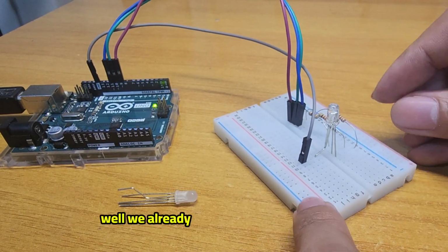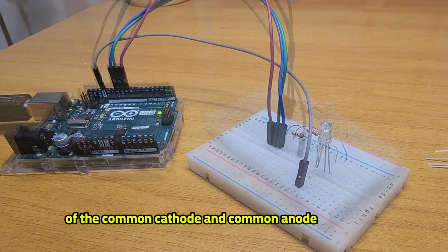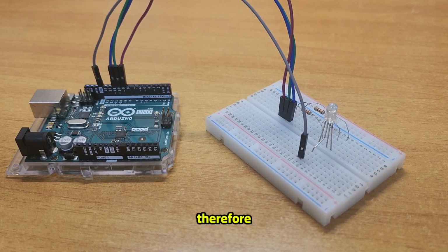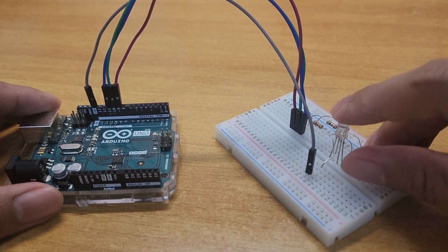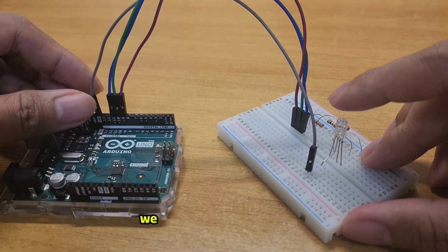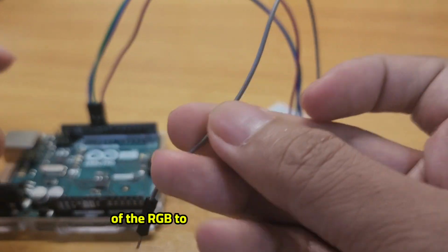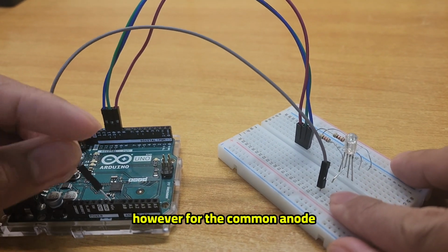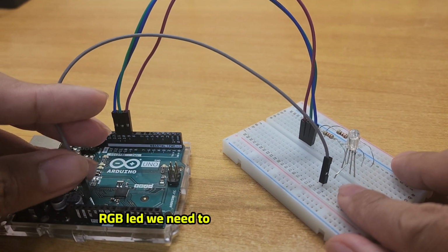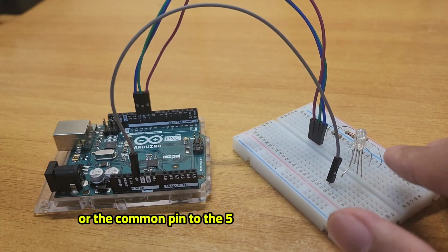Well, we already know that the common pin of the common cathode and common anode is different. Therefore, we need to change the physical connection with the Arduino pin. In the previous experiment, we connected the longest pin, or the common pin, of the RGB to the ground of the Arduino. However, for the common anode RGB LED, we need to connect this longest pin, or the common pin, to the 5V pin of the Arduino.